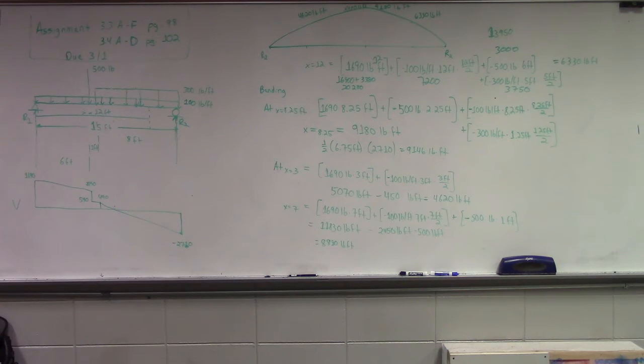So questions on constructing these moment diagrams? That was still that first question I asked you about, right? Yep. But keep in mind, the first set of homework, you already have the shear diagrams, right? So it's just transforming those shears into bending diagrams. And you won't typically have to determine the reactions for you. Okay?